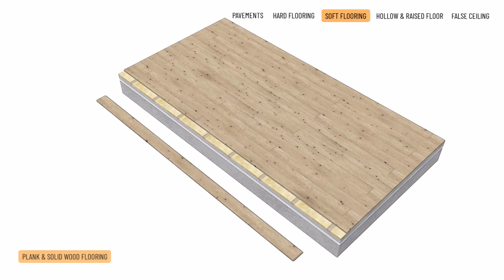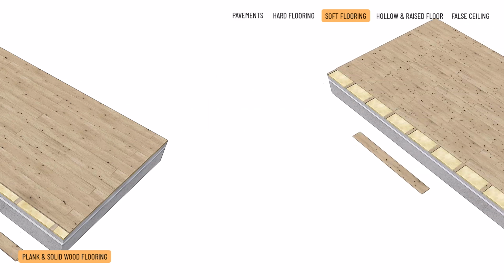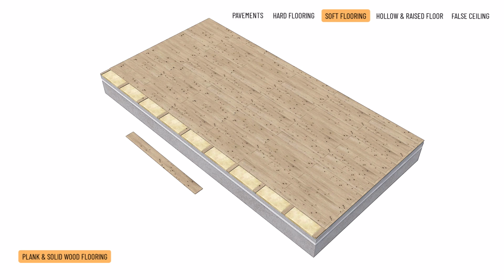Soft flooring, plank flooring and solid wood flooring. Plank flooring consists of hardwood planks that are 3 to 6 meters long, 80 to 150 millimeters wide, and 19 to 22 millimeters thick. Solid wood flooring features higher quality workmanship and smaller dimensions, 0.9 to 1.5 meters in length, 70 to 120 millimeters in width, and 16 to 22 millimeters in thickness.